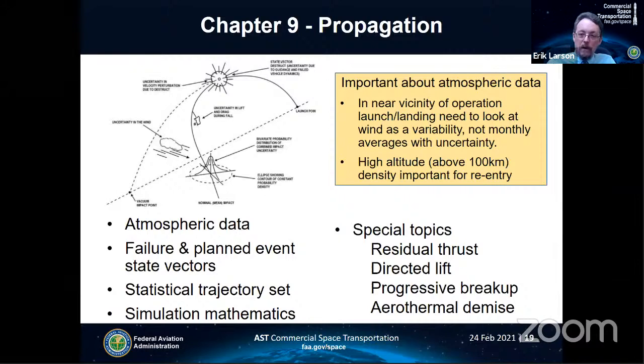So the uncertainty at launch time will be small, but some sort of sensitivity study or a launch day countdown analysis will be done with the right winds to account for that, because the uncertainty gets smaller, which can increase the probability of impact for areas that are directly under the trajectory, especially, which affects ships and aircraft hazard areas.